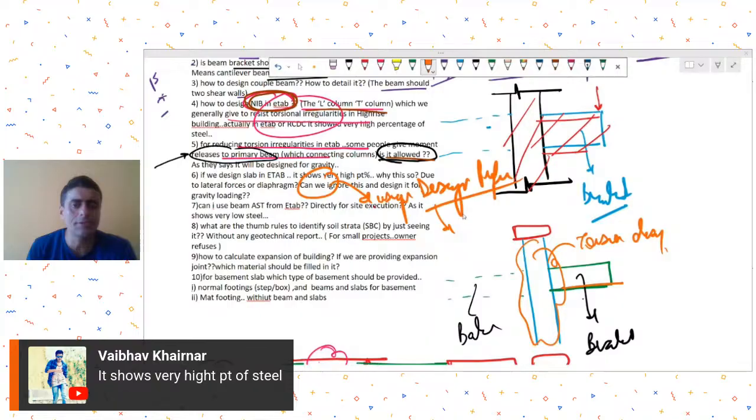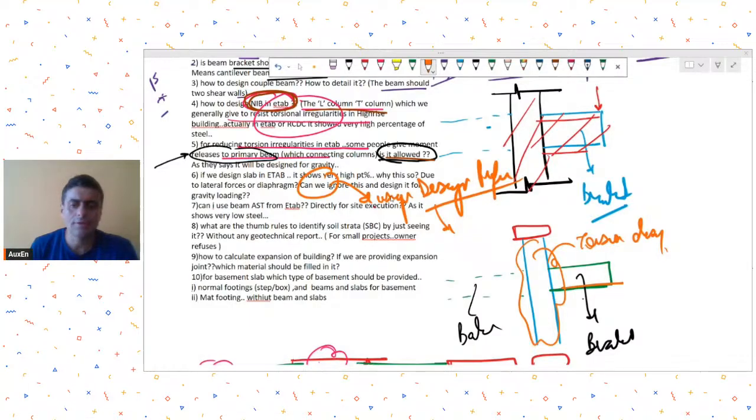What happens many times is that you may have defined, let's say, Fe 500 grade reinforcement, but if you don't give this design override before slab design, it will do the slab design for some different reinforcement grade. So please be very careful about this first: select the slab, go to design overrides, and check the reinforcement grade first thing.